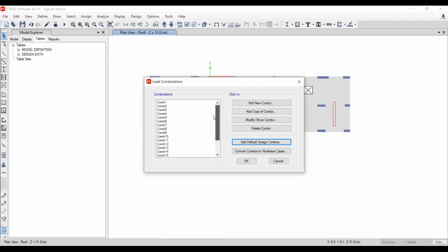So now we define all the load combinations. You can see and follow this step: 1.2, 1.6 live load, 1.2, 0.9 dead load, 1 wind load, earthquake will be enveloped. That's why I asked you to follow this one. 5.3.1, search for this.